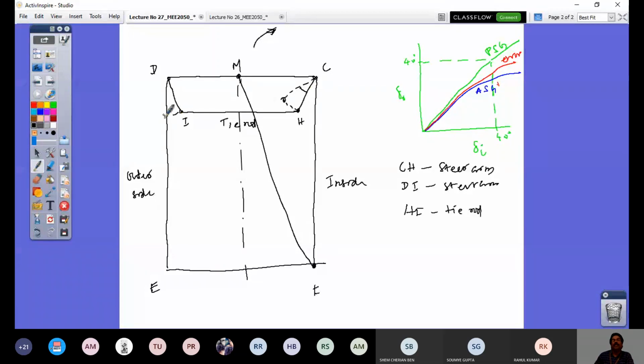I draw it, taking the tie rod distance with this as a center and cutting an arc on this. So this is the change in orientation of the tie rod and the corresponding change in the DI steer arm. This is the change from 0 to 30 degrees, say, for example. I'm taking that angle in increments to see whether there is any error.